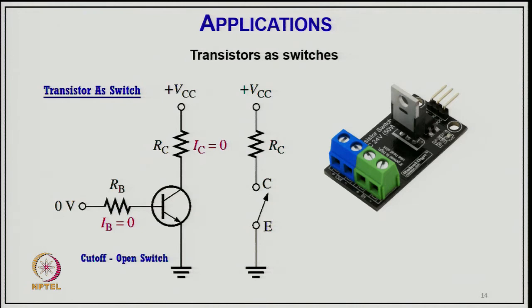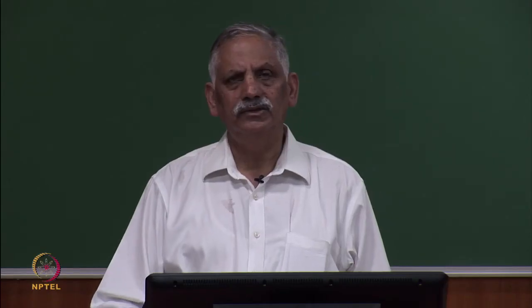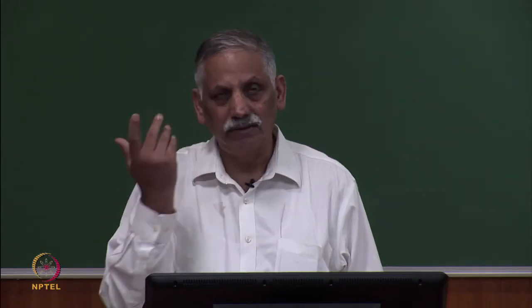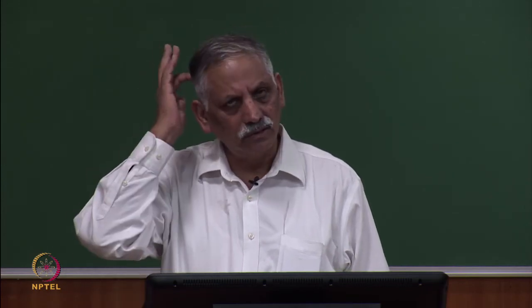Now, that was one side of application, this is another side of application of transistor. The transistor works as a switch, like a solid state switch, and the benefit of using a transistor as a switch is that it does not have a fixed number of operations. If you take any mechanical, electromechanical or electromagnetic switch, there is mechanical motion as well as the operation, and that causes bounce and heat on the contacts. There are physical contacts there, so the number of operations is fixed.